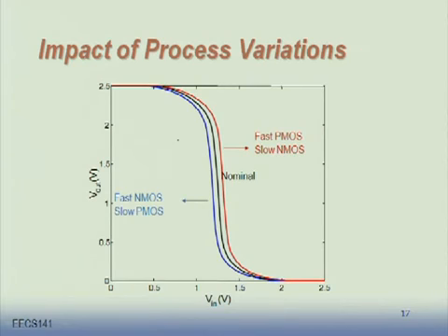It's not bigger. So when you manufacture a wafer or a number of wafers and plot a statistical distribution of VTs, you're typically going to get some Gaussian distribution. This is going to be typical. When the threshold turns out to be very high, that's going to be the worst case. That's going to be the slowest devices. That's why we call this a slow corner.